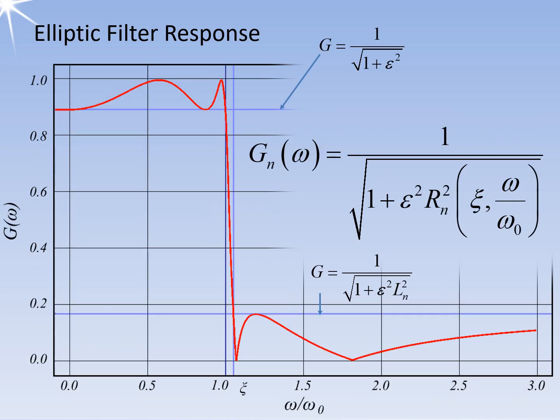An elliptic filter is a filter with equalized ripple behavior in both the passband and the stopband, that is commonly used in signal processing. This means that the amount of ripple in each band and the selectivity can be adjusted independently. The image illustrates the filter characteristics of a fourth-order elliptic filter with a steep transition between the passband and stopband.